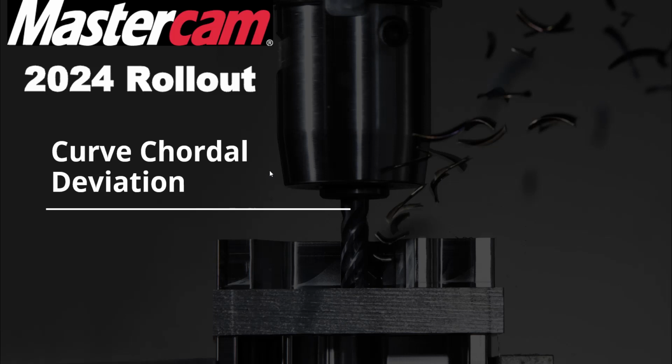That can be problematic. The normal direction of the face matters. There's some things that are unique to Flowline where they can be problematic, and there's ways of working around it, but what I would usually tell people, Flowline's great. If it works, great. If it doesn't work, instead of editing surfaces, rebuilding surfaces, surface finish blend is a great